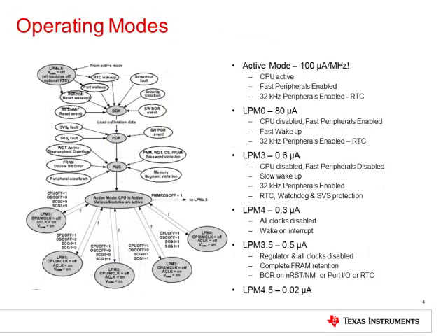This slide illustrates all of the sources of system reset, including a brownout reset or BOR, a power on reset or POR, and a power up clear or PUC. Different events trigger these reset signals and different initial conditions exist depending on which source triggered the reset.